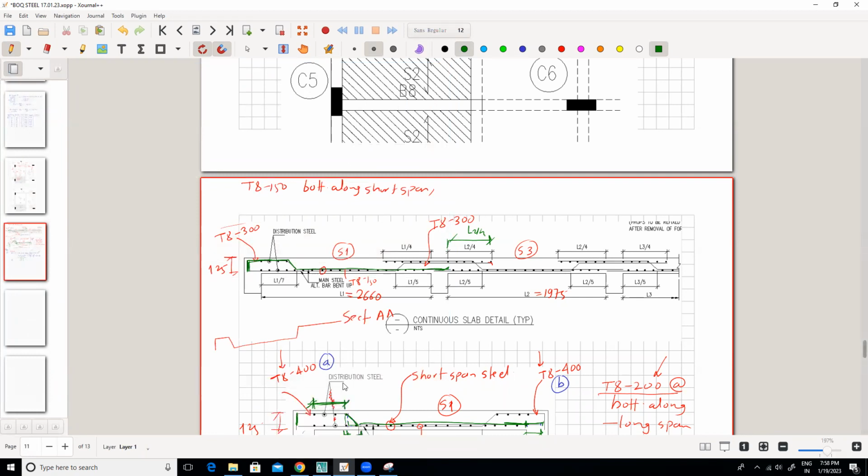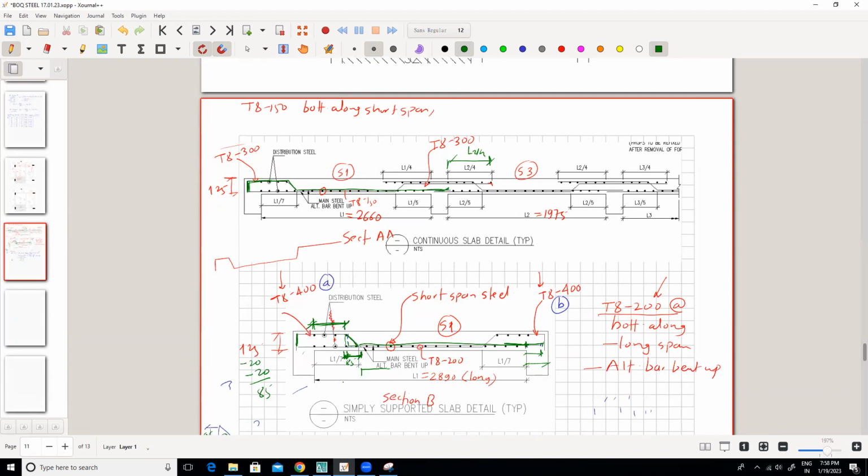Now, so this main steel you got, if it is continuous, then you will add this in this portion only. Here, when it is not continuous, there is a L here. And if it is continuous, then it continues in the next slab for L/4, right? So you will add that. Instead of this L, you will only add this L2/4. So this is the main steel calculation.